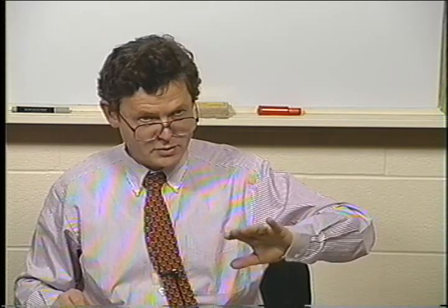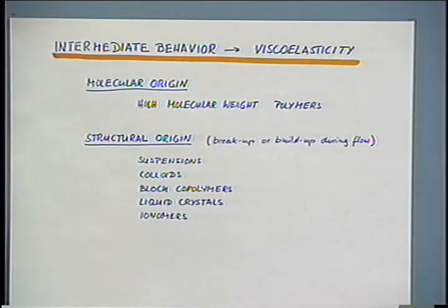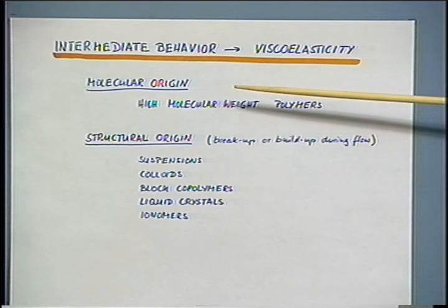And now let's go to the polymeric materials, the polymeric liquid, better to be more precise. And those materials have an intermediate behavior between liquid and solid. And that makes them really interesting to us. Those materials are called viscoelastic. We say it's a viscoelasticity phenomenon, or when you look at maybe Ferry's book, it's a whole book on linear viscoelasticity. We have to specify what this is in a moment. But basically, the behavior between the ideal Hookean and the ideal Newtonian behavior, this viscoelastic behavior, has an interesting origin, and